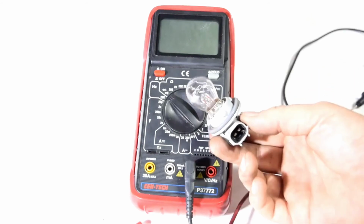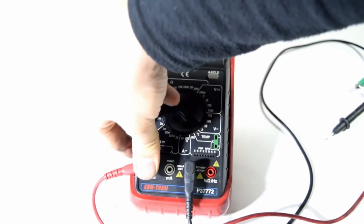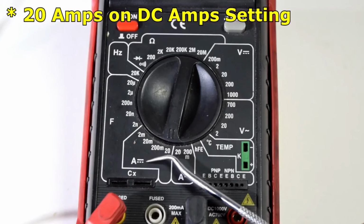Also, if you're unsure about the amount of amps you'll be measuring, but you know it's less than 20 amps, you can always start with this higher one and then move down for a more precise reading. So for this example, we're going to measure and see how many amps this little light bulb uses. So we put our red test lead in this setting. And next we're going to set our dial, and since this light bulb is battery powered, we're going to set it to 20 amps on the DC voltage setting.